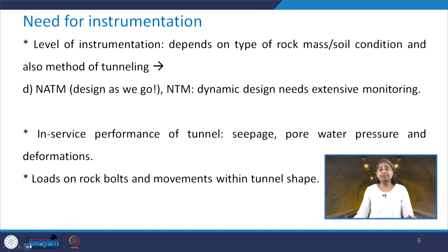Another aspect: we have learnt about NATM and NTM, the New Austrian Tunneling Method and the Norwegian Tunneling Method. There also instrumentation is needed, because the philosophy of NATM is that we design as we go. And NTM is related to dynamic design, which needs extensive monitoring.